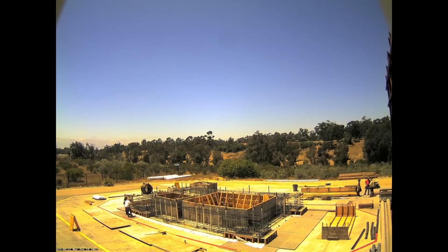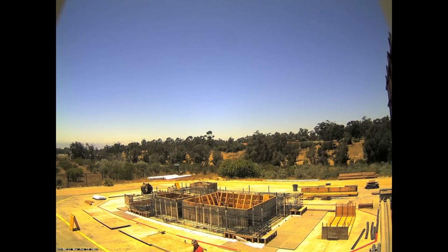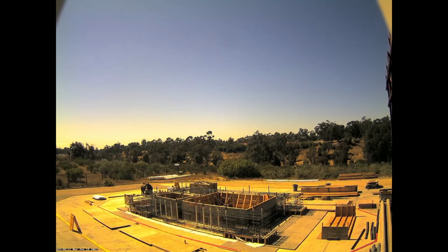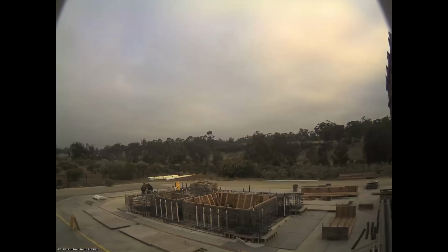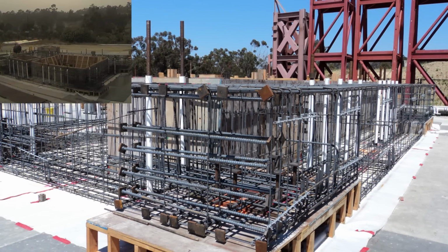In this project, after the base isolated building was tested, the isolators were removed and the 5-storey building was fixed directly to the shake table. This was done in order to compare the seismic performance of the base isolated building in contrast to the building fixed to the foundation. Concrete cast-in-place construction requires the use of steel reinforcing bars, simply termed rebar in the field,